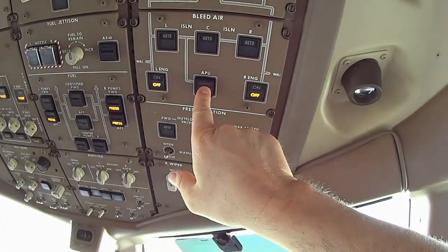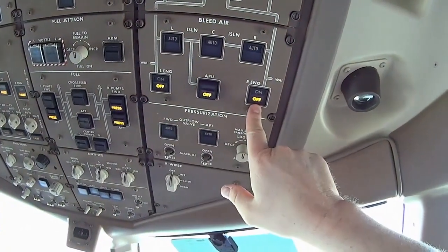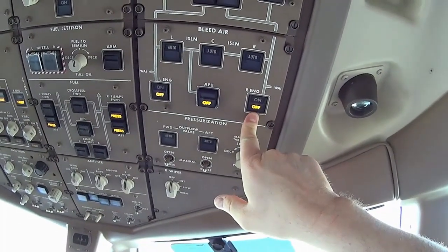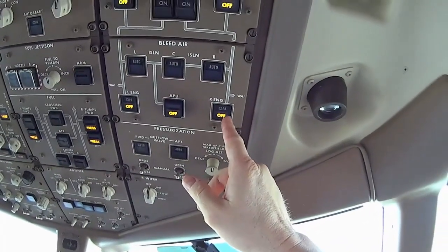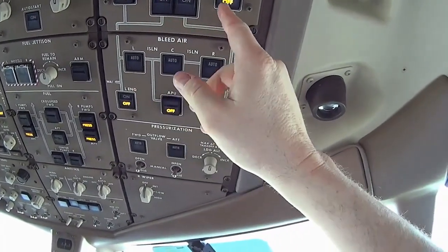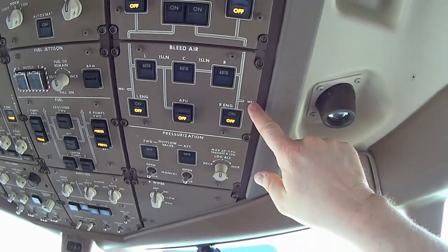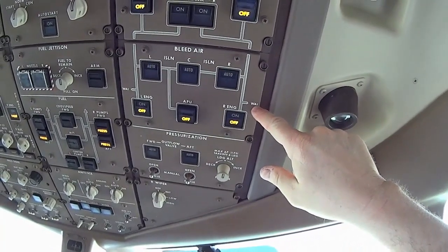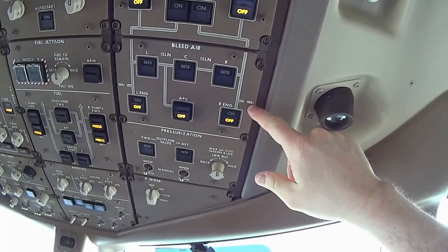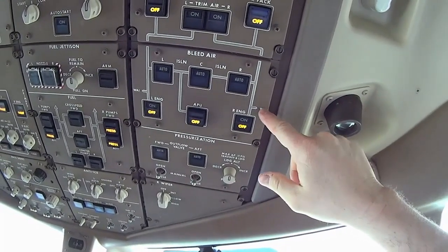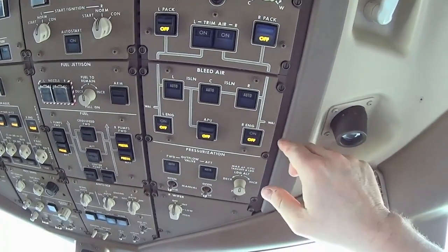And this is the APU bleed air. These are the engine bleed airs. Obviously we won't have those on right now because the engines aren't running. When we go into flight mode and the engines are running, these take over and this is shut down. And then you can see on the panel, the system schematic is drawn on the panel to what it feeds. This is the wing anti-ice. These will be like the leading edge that I showed you on the engine and the leading edge of the airplane. The leading edges of the horizontal and vertical, all the shiny metal on those, is the heated leading edges. So that'll be wing anti-ice. So that goes to those valves.